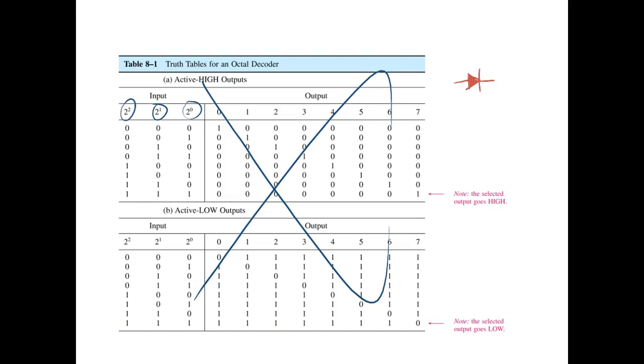But an LED is designed to light up when the holes and the electrons combine at the barrier. They actually emit photons. They actually emit energy. It actually causes energy release. The problem with silicon is that it does not release very many photons, and the photons it releases are at a wavelength we couldn't see anyway. So what they do, instead of using silicon, they use gallium.